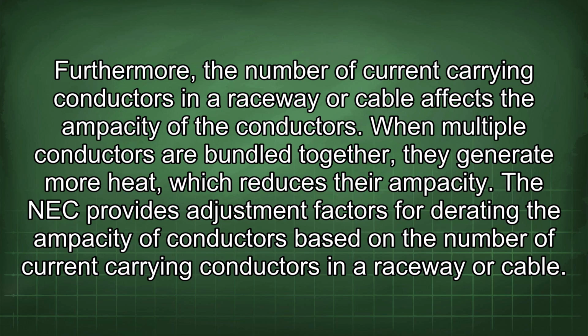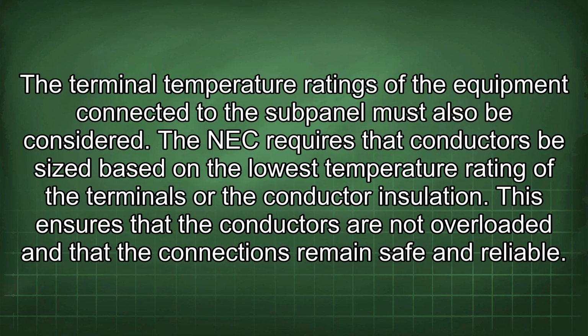The NEC provides adjustment factors for derating the ampacity of conductors based on the number of current carrying conductors in a raceway or cable. The terminal temperature ratings of the equipment connected to the subpanel must also be considered. The NEC requires that conductors be sized based on the lowest temperature rating of the terminals or the conductor insulation. This ensures that the conductors are not overloaded and that the connections remain safe and reliable.